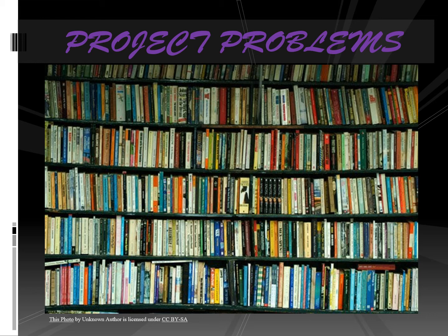Experimenting on fillet welds with known subsurface discontinuities proved to be successful with phased array. PAUT clearly has benefits in the quality assurance fields, and while the holes in Australian standards exist, internal procedures will be the only way to perform inspections without Australian standards.